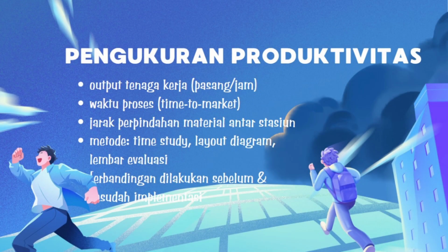Productivity in this study was measured using several indicators. First, they measured the output of labor by calculating how many pairs of shoes were produced per hour per worker. Second, they measured time-related factors such as the time needed to prepare materials, process assembly, and transfer items between stations. Third, they measured the distance of material movement in meters to assess the efficiency of the new layout. These indicators were evaluated before and after implementing the lean model using tools such as time studies, diagrams, and standard worksheets. The combination of quantitative and qualitative data gives a complete picture of how the improvement affected the company.